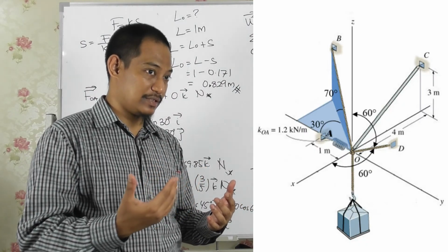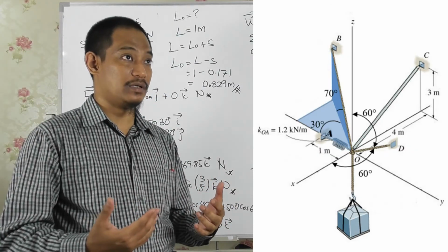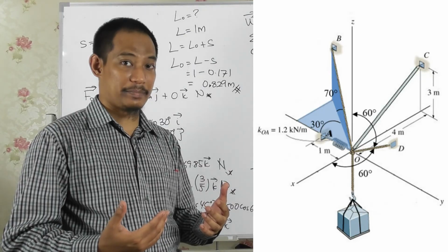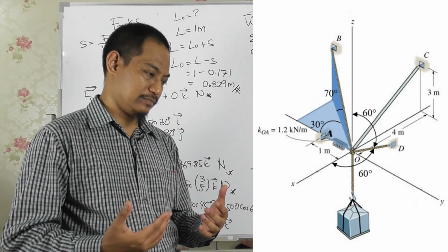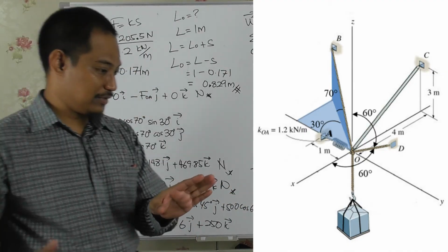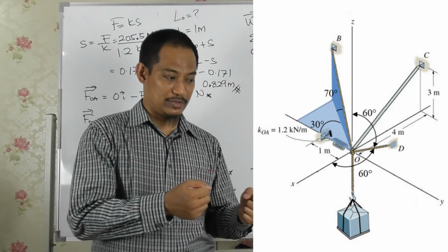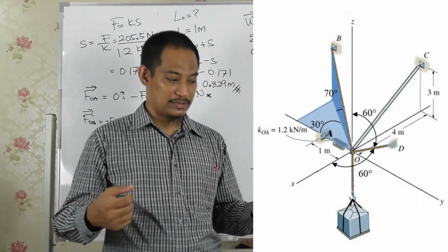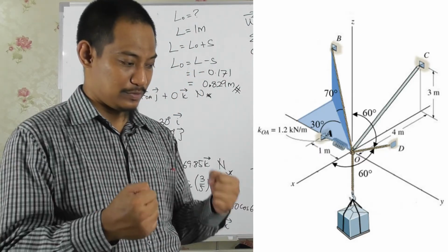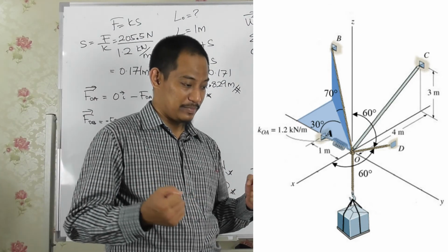And just that the rod will be under compression. No, sorry, the force is in that direction. Okay, the rod will be under tension, right? Because it is being pulled in the other direction, so it will maintain equilibrium by being under tension.